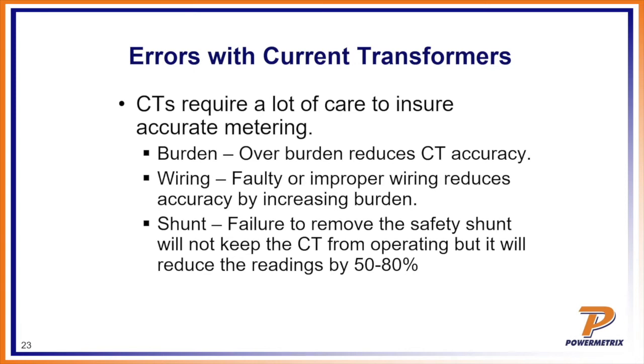Let's say you're in an environment near the coast. Corrosion is a real big problem because that can cause more resistance in the wiring. Also, people forget about the actual wiring gauge. So they'll use a smaller gauge wire, whatever they had off the truck, run that wire, and that can be a problem as well, and we'll talk about that.